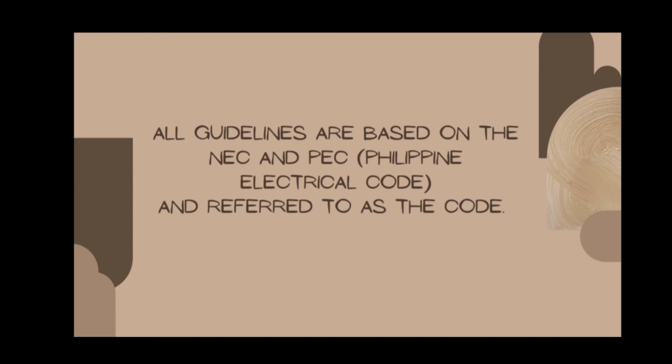8. In bedrooms, supply 2 duplex outlets at each side of the bed location to accommodate electric blanket, clocks, radios, lamps, and other such appliances. In rooms without overhead lights, provide switch control for one half of a strategically located receptacle that is intended to supply a lamp. 9. Convenience outlets, though counted as part of the general lighting load, shall be limited to 6 convenience outlets on a 15 amperes circuit and 8 convenience outlets on a 20 amperes circuit.